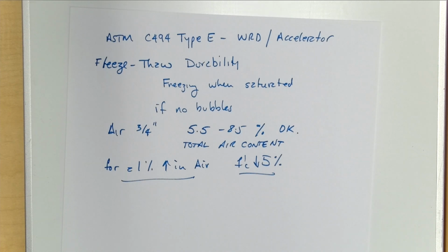One for air-entrained and one for non-air-entrained concrete. And for a given strength, we need a lower water to cement ratio for air-entrained concrete in order to get the same strength. And that's because what's the strength of the air bubbles? Not particularly high. So we have this air problem that we have to deal with.